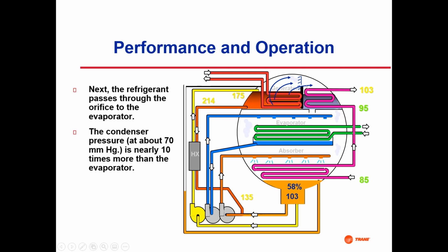And this pressure forces the water flow through this orifice. So we have low pressure down here, and then we get that expansion. It's kind of the expansion valve for these orifices where we drop pressure, we vaporize a little bit of the water, and that cools the rest of it.